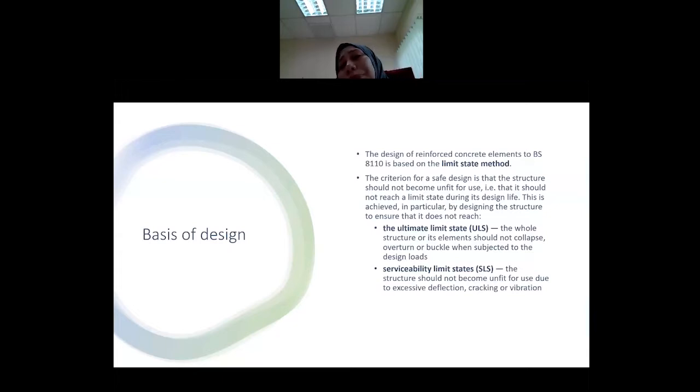Then we have the serviceability limit state. The structure should not become unfit for use due to excessive deflection, cracking and vibration. Serviceability limit state is more appearance wise. Cracking is not pretty, but excessive cracking can also cause the structure to collapse.